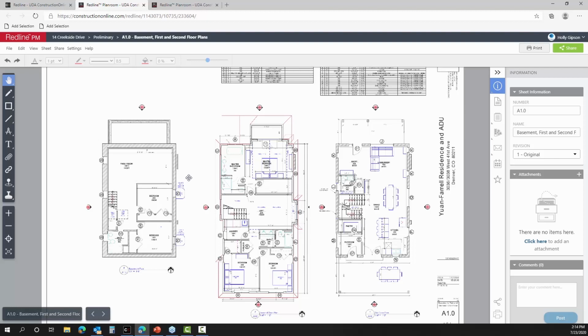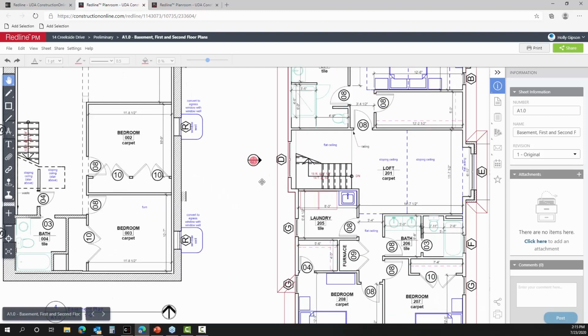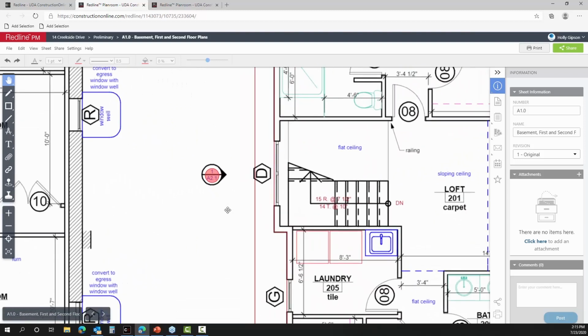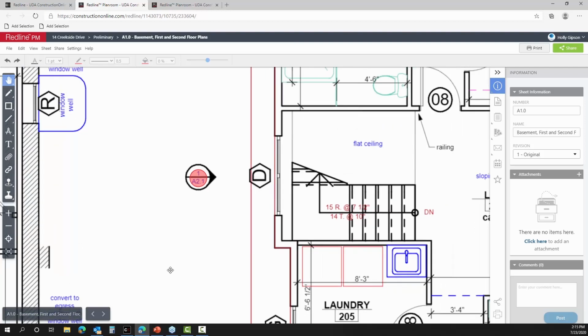Definitely. And one of the things that you'll find, if we take a look at my sheet here, I really haven't added any markups yet. This is a fresh set, but what we are seeing are these red shaded dots or areas throughout the plan. What this is letting me know is that those are the areas where those are linked. So our typical process might be to first zoom in really closely, see which sheet is being referenced, and maybe if we're using a digital system, flip over and find that particular sheet. In this case, it looks like it's a link to an elevation.